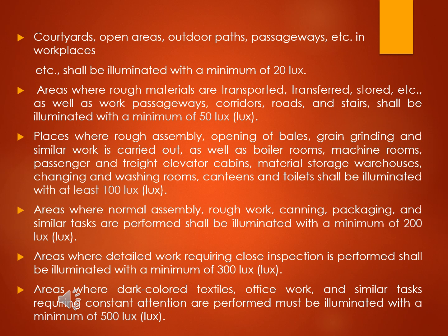Places where rough assembly, opening of bales, grain grinding, and similar work is carried out, as well as boiler rooms, machine rooms, passenger and freight elevator cabins, material storage warehouses, changing and washing rooms, canteens, and toilets shall be illuminated with at least 100 lux.